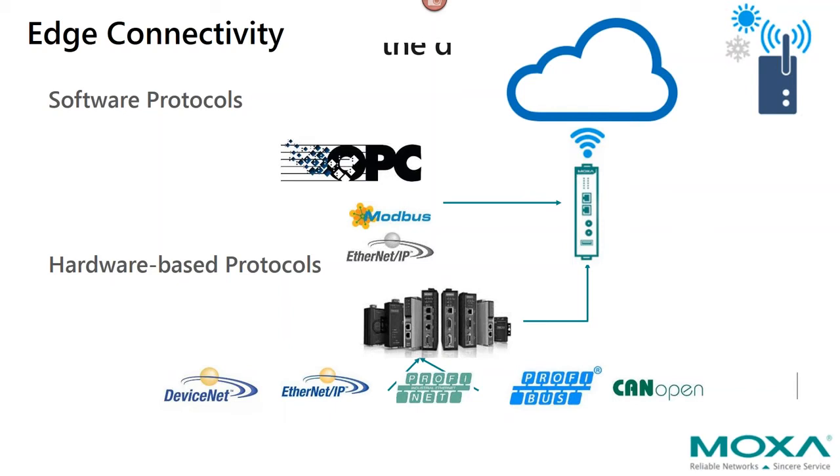For these cases, Moxa offers our industrial protocol gateways. These can be used to convert data to Ethernet, and then the Industrial IoT Edge Gateway can publish this to one of the cloud applications using publish-subscribe protocols like MQTT. So again, with a solution that's more distributed and more OT-centric, you can connect existing protocols to the cloud. It might just not be as simple as a single set of software solving all problems.